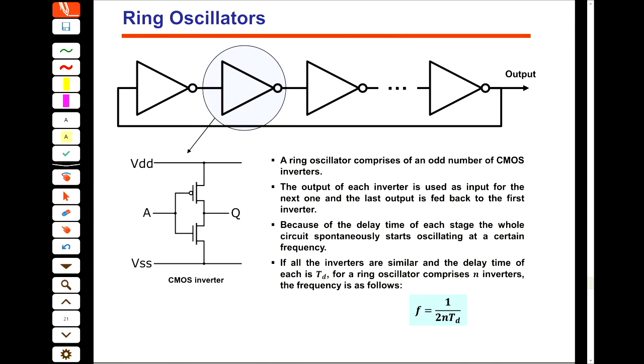All right. We can make oscillators out of just a ring of inverters. So the inverter circuit is this one, a CMOS inverter. This CMOS inverter, definitely based on the technology that we use, has a delay. I mean, when we are changing the input, the output changes after a delay. So it depends on which process you are using, the delay is different, okay?